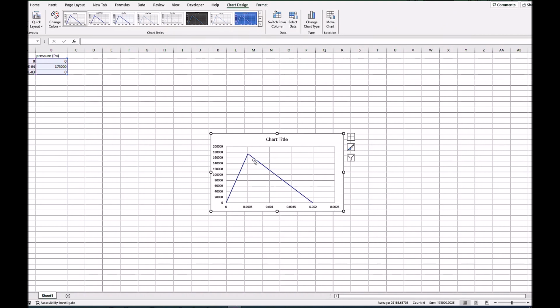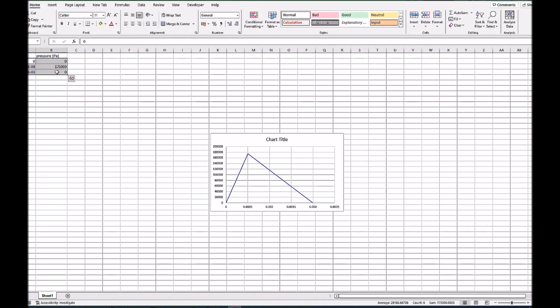As you remember, there could be many stages, and it can also go in this way with a non-linear function. In this case, we keep our life simple. Everything is in milliseconds, so we need to model everything in ABAQUS in milliseconds. So this is kind of an amplitude function. I already have videos on how to define amplitude in ABAQUS CAE, so you can look at those, but I will do it again from scratch in this case.